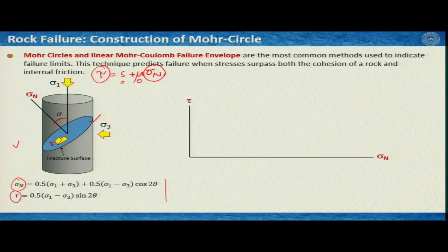If we do an unconfined uniaxial test, then it is very important that at that time sigma 3 would be 0, and then sigma 1 has a value when the rock produces the fracture. So, if I take these two points, here is sigma 3, which is the atmospheric pressure, or you can say no value if you do it in vacuum.